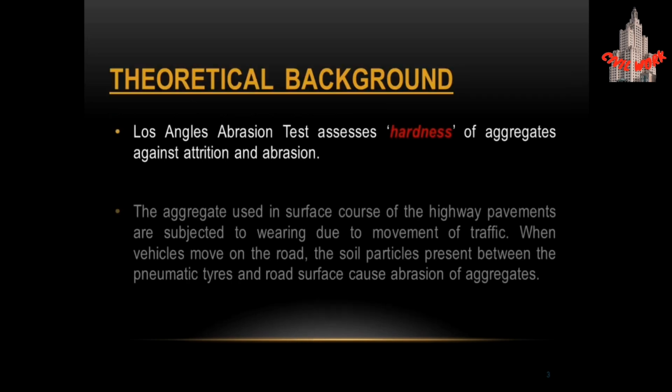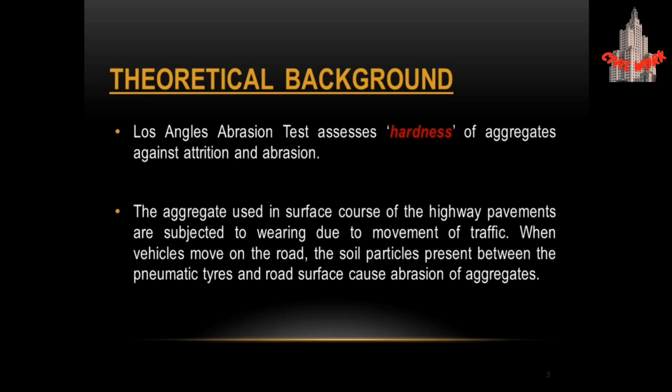Coming towards the theoretical background, Los Angeles test measures hardness of aggregate. Hardness refers to its resistance to wear, scratching, and abrasion. It's an important property in the field of construction as it affects their durability and performance in various applications.